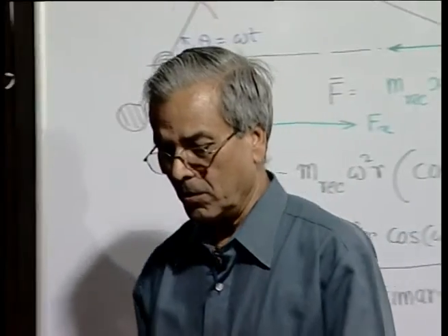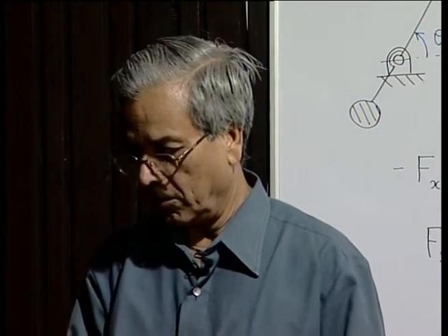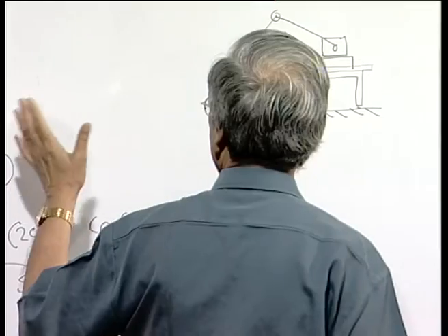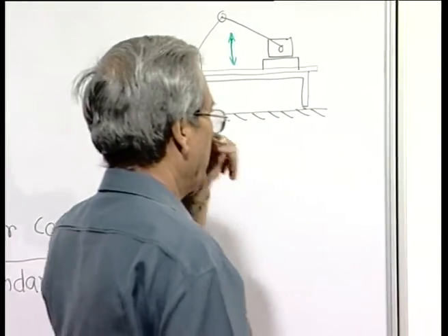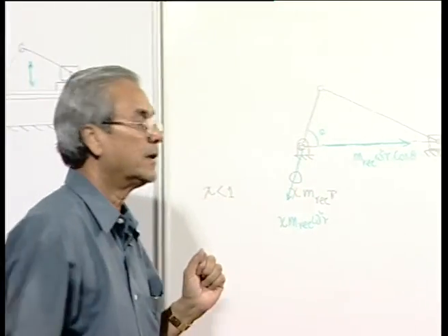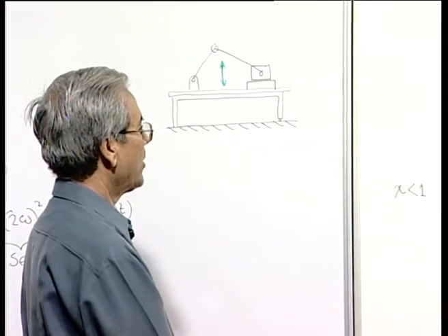However, you can also stretch your imagination and consider a complete balancing of the unbalanced force. If we have to do complete balancing, then obviously two things you have to keep in mind: that we have to neutralize the force without generating a new force, as we have done in this case by adding a simple counterweight.